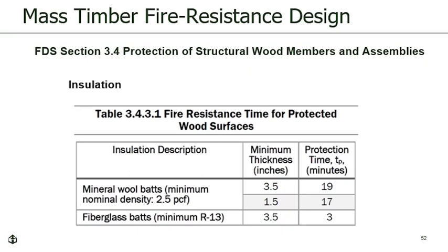I also want to mention that unlike protection time from wood and gypsum, the protection time associated with insulation is not cumulative, even when there are multiple layers of insulation used within the assembly. You can only claim the protection from one of the layers of insulation.